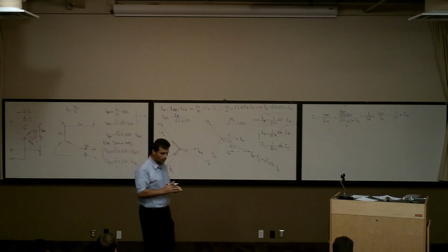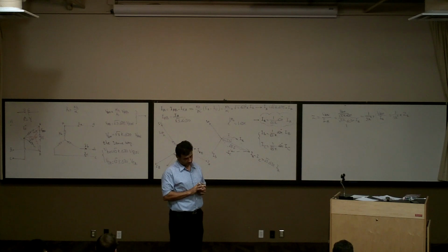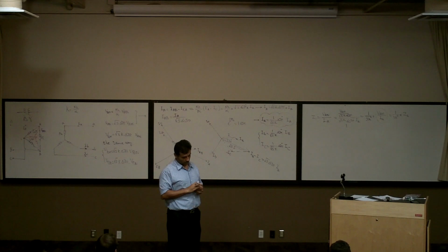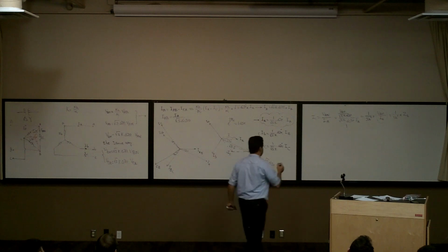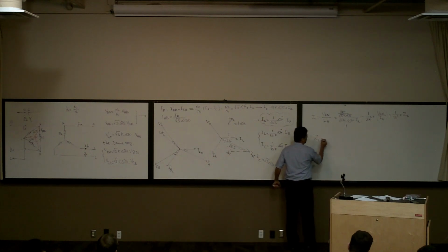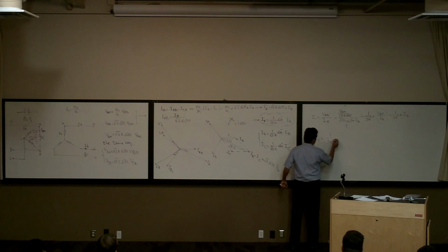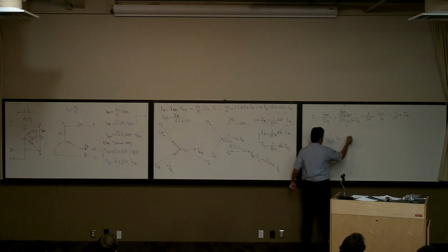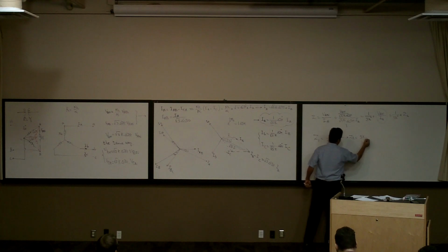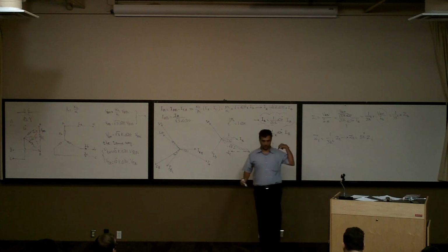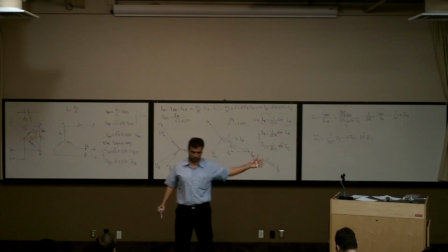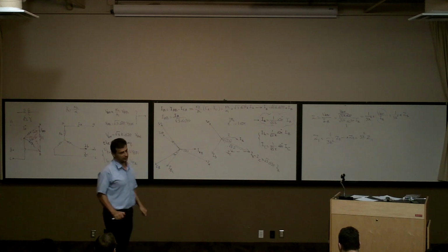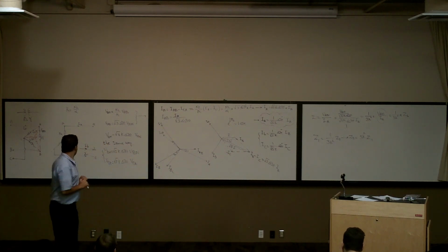So you're referring the primary to the secondary? Is that what you're doing right now? And the impedance transfer from primary to secondary, right? Right. We can go either from primary to secondary. This equation you get. I'm saying Z1 is equal to 1 over 3K2 Z2. Or you can say Z2 is equal to 3K2, sorry, K to the power of 2 Z1. You can go either way, you know. If you want to go from this side to that side or from that side to this side, you use this equation. So this is the impedance transfer for the delta Y connection.